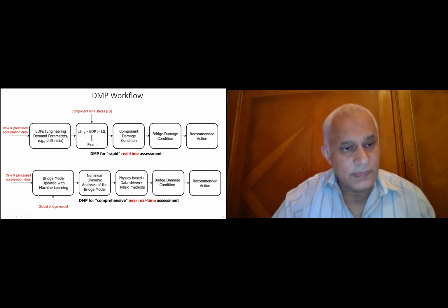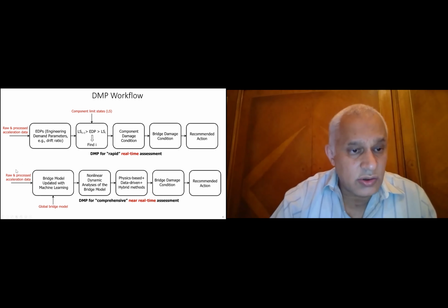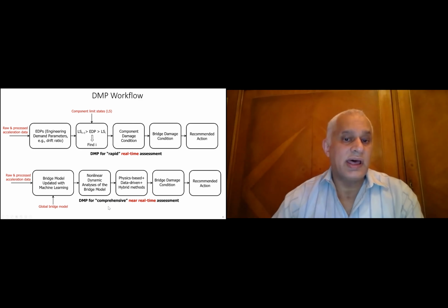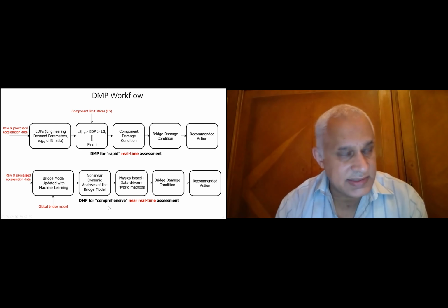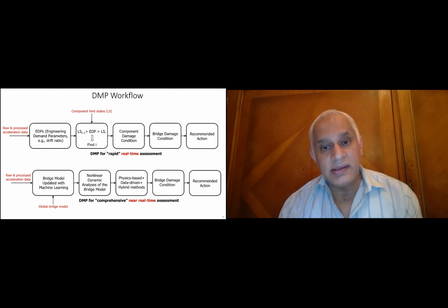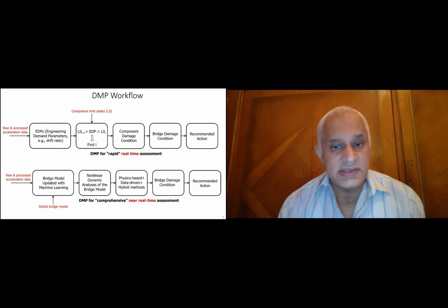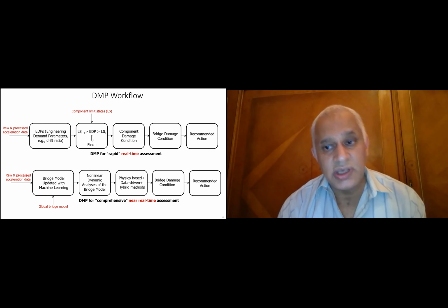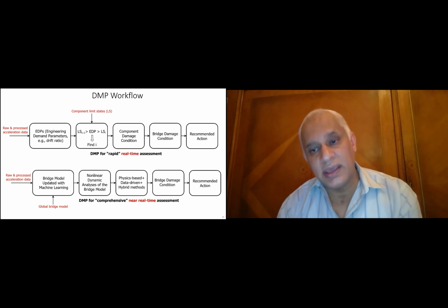On the other hand, for the near real time, the main feature that is added is the global bridge model that is used in conjunction with the data to perform nonlinear dynamic analysis of the bridge model, and then a combination of physics-based and data-driven, or a hybrid method, we can use to assess the bridge damage condition. And again, we provide the recommended action.